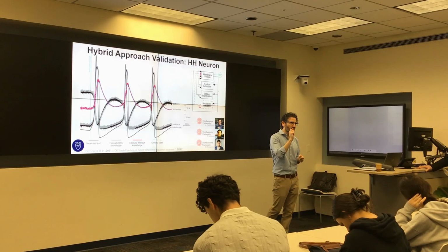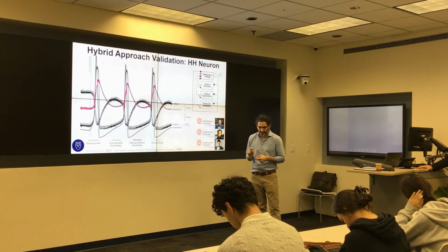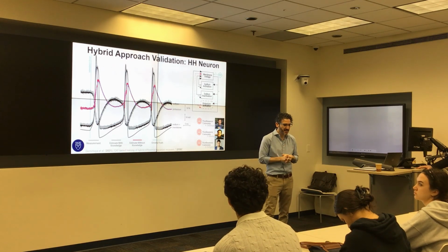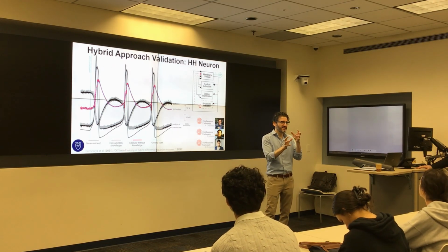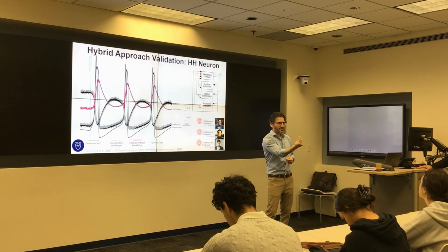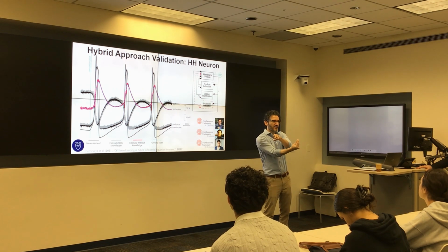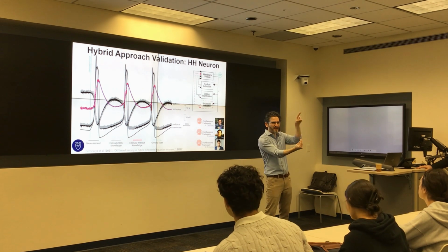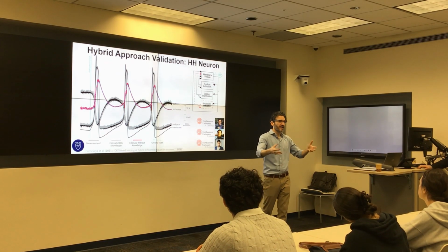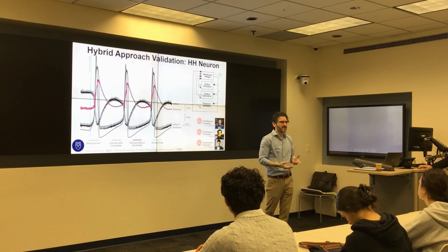Now, the caveat to that is there are regions of the state space where that doesn't quite hold. The idea behind the Kalman filter predicting where your state is next is that you take a couple of guesses, kind of. You get a measurement that you're right here, and the Kalman filter says, well, that's where the measurement said, so you could be anywhere here. Mostly we're going to guess you're around here, but you could be out here, you could be out here. Now that works fine when you're driving in your car and GPS is running, because if you're over here, you're just on that street. If you're over here, you're on that street.